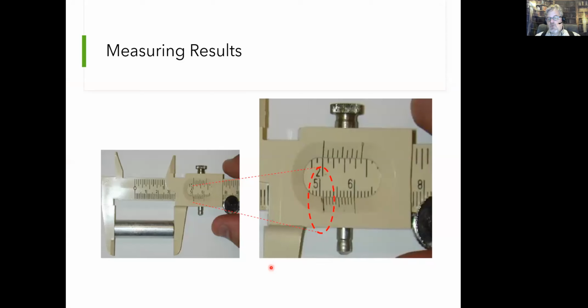So typically we would measure the length with a caliper. If it's a small part, it might be a tape measure. If it's a large part, or if you need a very accurate measurement, you might use some of the larger calipers or other measurement systems like a laser system. But typically there's a measurement step that occurs right after you chop the part off.